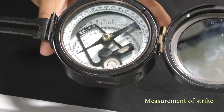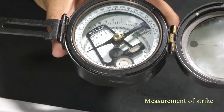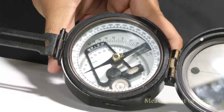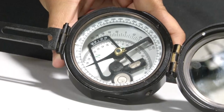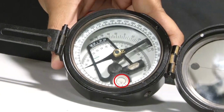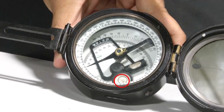Now to measure the strike, we place this basal edge of the compass against the plane we want to measure. Once we do this, we have to make sure that the compass is in a horizontal position. The horizontality of the compass is ensured when the bubble in the circular level is in the center, which is now the case.